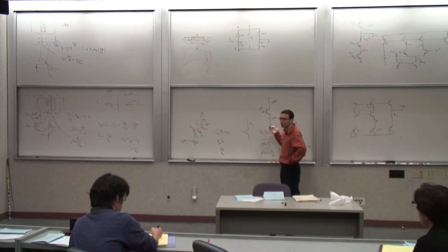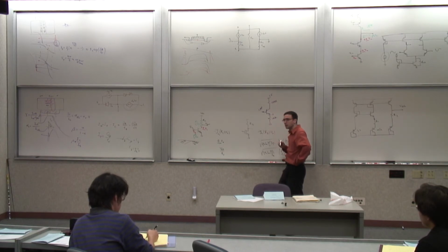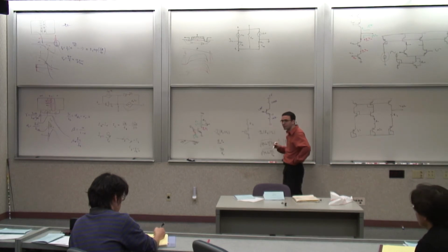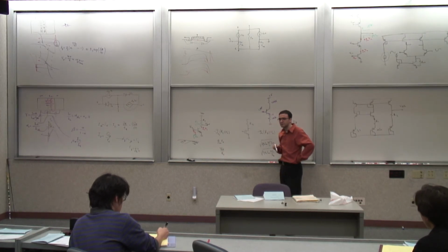Well, okay, this is a VBE drop anyway. So this is about whether or not it's in forward active region. As long as this voltage is higher than that voltage, it's about 0.7, 0.8 volts. So this voltage is about 1 volt, and I have to tell you what this is applied. Let's say it's 5 volts. So if this is 1 volt, 1K, this is about 1 milliamp, right? But what is this voltage? If that's 1 milliamp, we calculate the predicted current from that. So it's 1 milliamp.